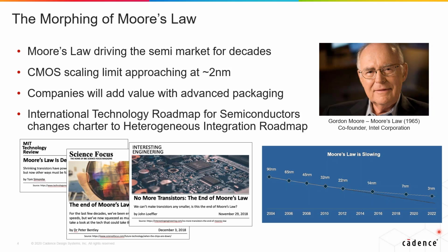Briefly, we are in the semiconductor industry, so we should review Moore's law. It has dominated our semiconductor industry development for maybe half a century. Basically it says that between 18 and 20 months, the critical size will shrink in half, or the clock rate will double. But recently we know Moore's law has been hitting the physical limit. If we're talking about 2 nanometers, it's just a few layers of copper atoms or a few layers of silicon dioxide.